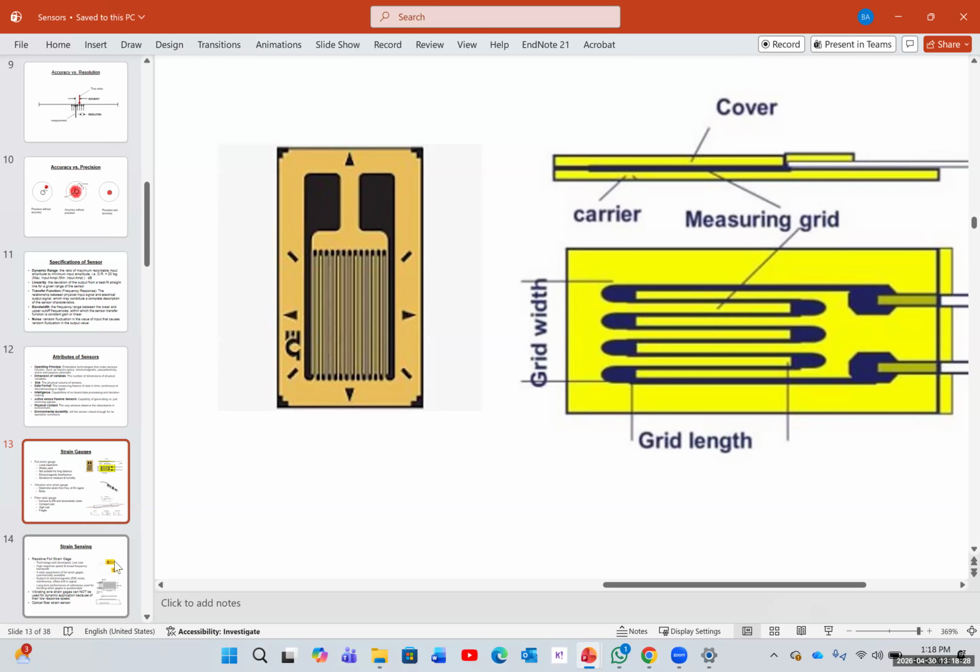So what happens if you make a coil or a mesh like this? It acts like an antenna. So all the magnetic field that you have around you is going to have some effect on this. So this technically acts like a magnetic receiver as well, like an antenna, and it produces a little bit of current. And the current difference that we have when we have a strain gauge is very small, by the way. Imagine you have this acting like the magnetic receiver or antenna as well. So that current is also induced, and you're going to have error.